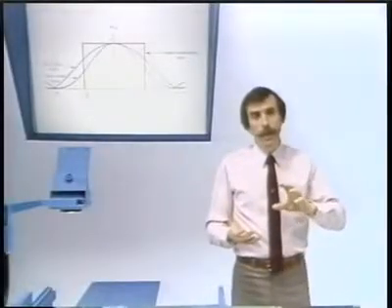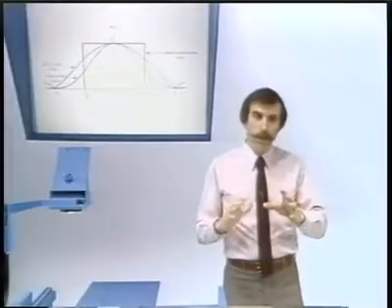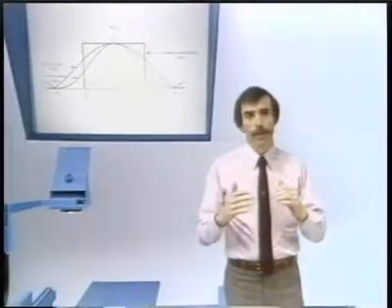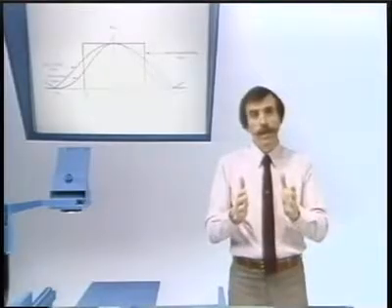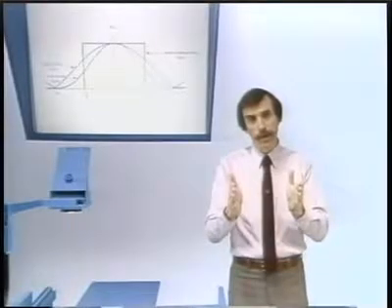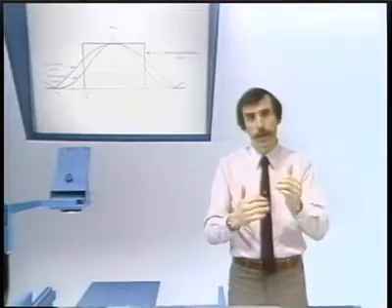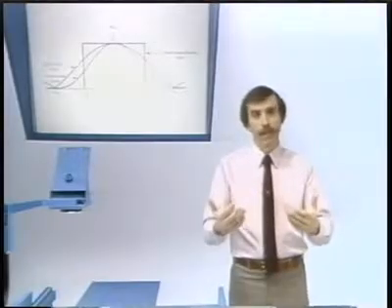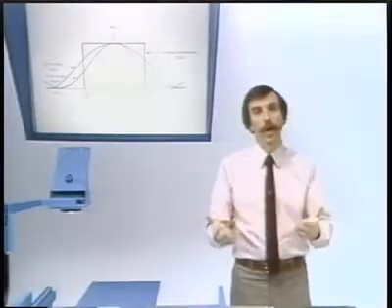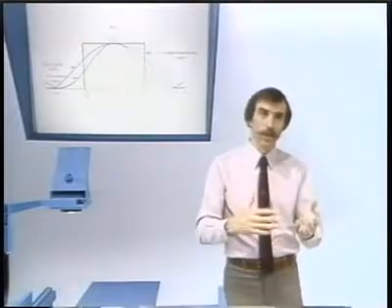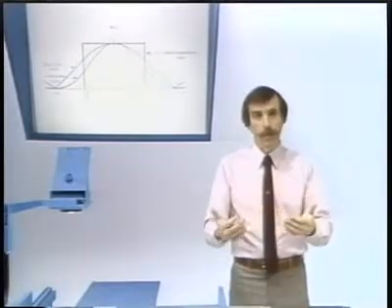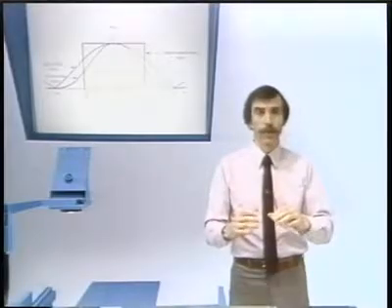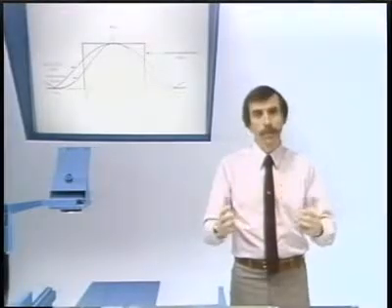Okay, to emphasize these effects even more, what I'd like to do is go through basically the same sequence again, but in this case what we'll do is double the sample spacing both horizontally and vertically. This of course means that we'll be even more highly undersampled than in the ones that I previously showed, and so the result of the reconstructions with some low-pass filtering will be a much more low-pass filtered image.